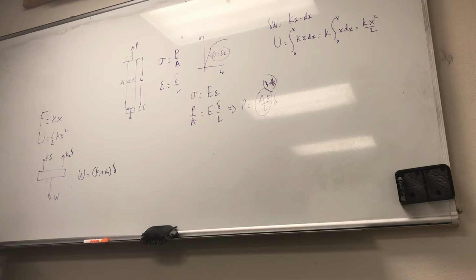Yeah. K equivalent is G d^4 over 8 N D cubed, okay? So since the 3 springs are identical and parallel, the equivalent spring constant of the suspension is given by 3 times this, because they add up, and you get 120,000 newtons per meter.